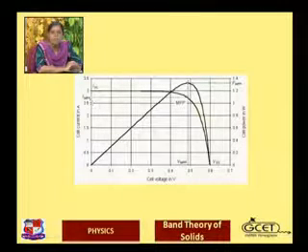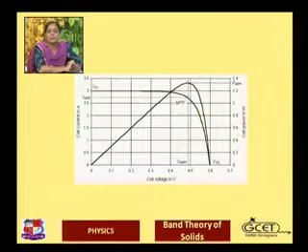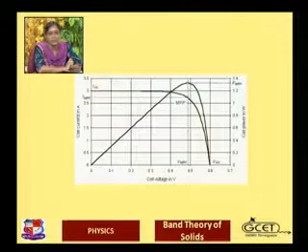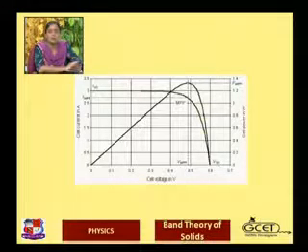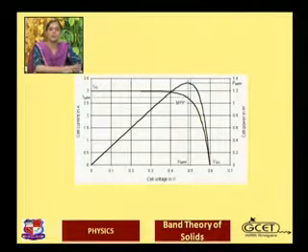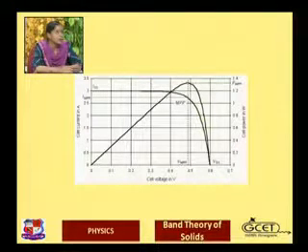This IMPP and VMPP play a major role in determining the efficiency of the solar cell, and these two curves, the VI characteristics and the power curve, give the maximum information about the given solar cell. So whenever a solar cell is used in any application, these two curves are to be plotted before joining the solar cell into the application.